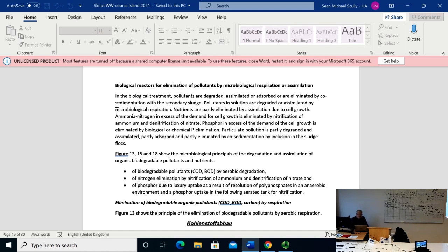They have to be absorbed, because when you go into the final clarifier, you have all those flocks from the activated sludge. When those flocks sedimentate, they act like a filter. So those flocks co-sedimentate other flocks that are maybe not activated sludge, but just inert biological material that's not really biodegradable.